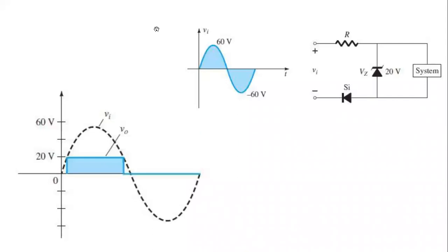Similarly in the reverse bias condition, my student, it will be minus, it will be plus. So the current will flow in this direction, in the anti-clockwise direction. At that time, it will be open circuited because the silicon diode is now in reverse bias condition.